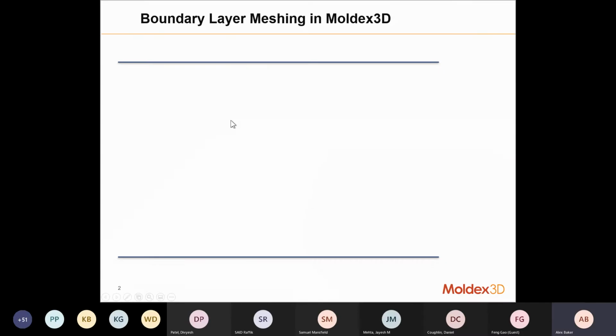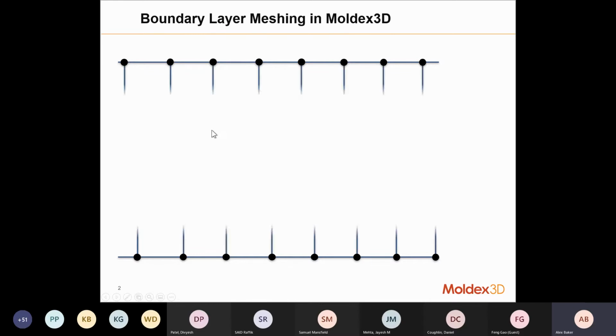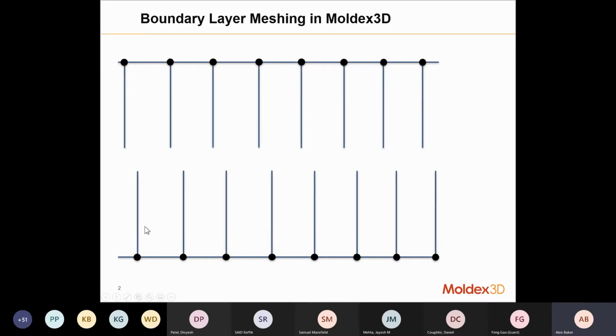All right. So every surface set on your geometry has an upper and lower bound. So in every location of your geometry, you have either an upper and lower surface, a left and right surface, a front and back surface, whatever you want to consider it. You always have an upper and lower bound. What we just did in the node seeding was we put a bunch of nodes across the upper bound and the lower bound. That creates our surface mesh. The surface mesh nodes are then going to be extruded from the top side downwards and from the bottom side upwards to create a 3-layer structure.